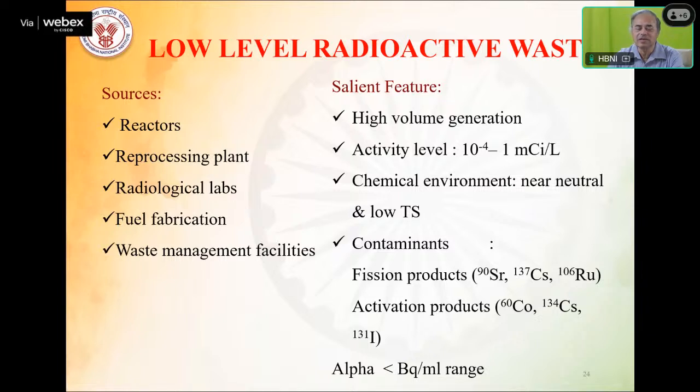So basically that contains a very small level of radioactivity. So it is low level liquid waste. But as you see, people are required to take a bath also at times. They are required to wash their hands or feet. So the volume of low level liquid waste generated is high. Compared to the HLW, volume is very high here. Their activity is high, here volume is high. Activity level is very small, that is ranging from 10 to the power minus 4 to 1 millicurie per liter.